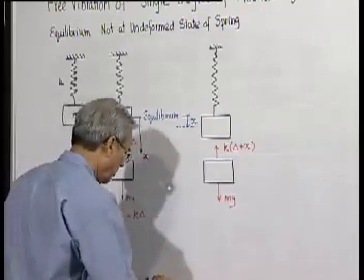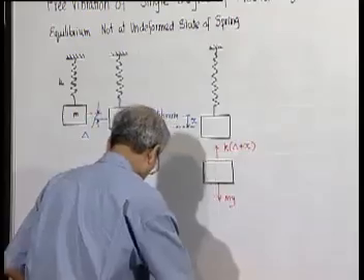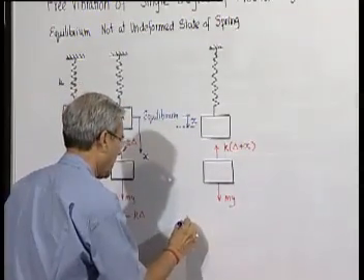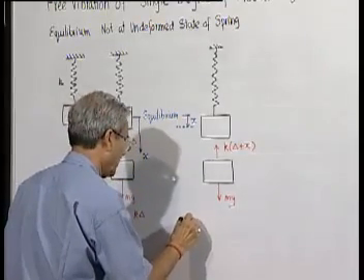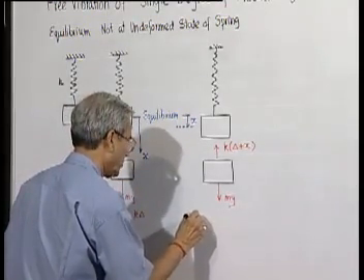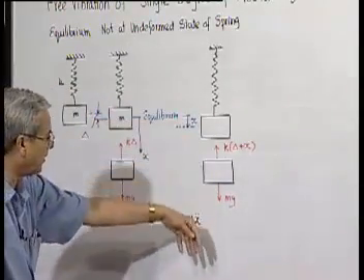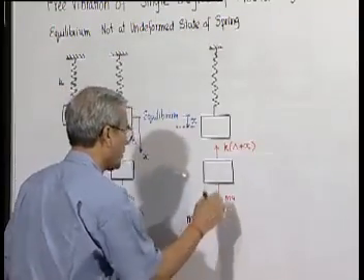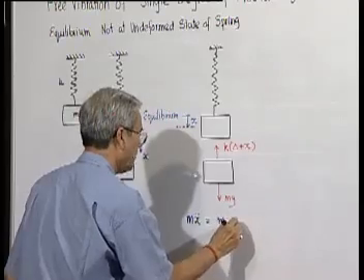So now the equation in this direction will be m x double dot, the mass into the acceleration of the body in this direction, and that must be equal to the total force in this positive x direction, that is mg minus k into delta plus x.